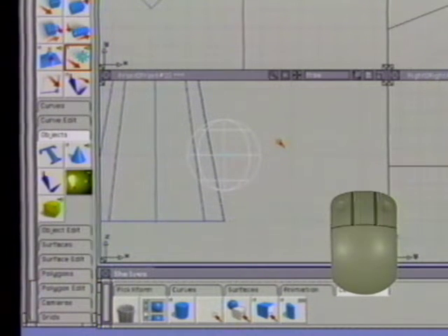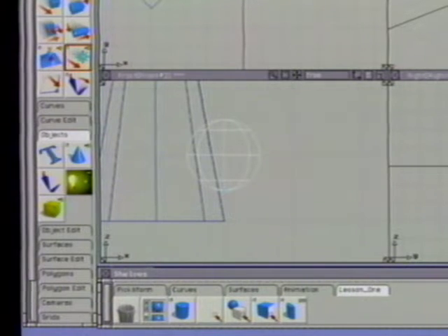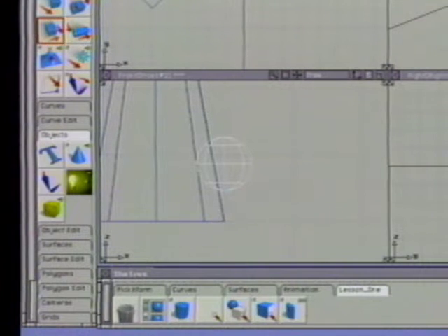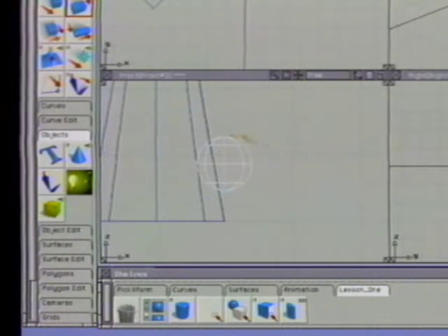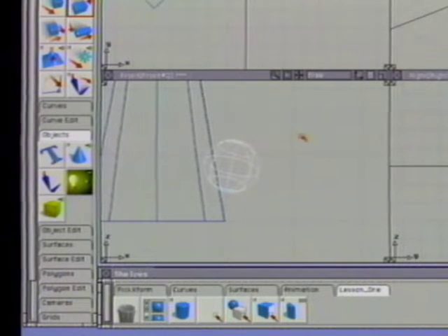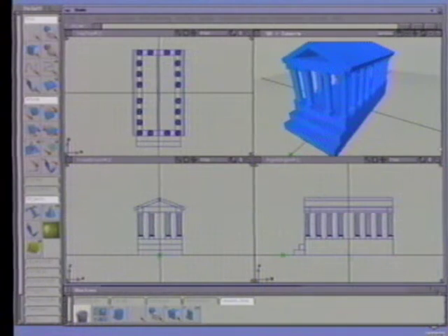Now go to the Xform section of the tool palette and choose Set Pivot. Click Drag with the right mouse button to move the pivot to the base of the sphere. From the Xform section of the tool palette, select the Scale tool. Click Drag to scale it. The sphere scales based on this new pivot. Any rotations that take place will also take place using the pivot as the center of the rotation axis lines. You can separate the rotation pivot from the scaling pivot, but in general you will keep them together. Pivots are an important part of using the Xform functions, and you should learn to use them to your advantage.